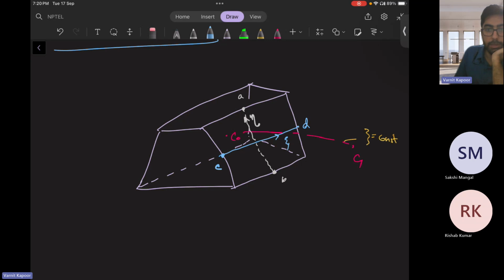So far we had only A and B coordinates. We have two more coordinates, C and D. So in total, we have four vertices, A, B, C, D, where these eta and xi need to be calculated. So if we have to write Γ grad φ dot A_f in a 3D structured mesh, the gradients will look like a three-term system. Earlier we had two terms, primary gradient and secondary gradient. But here, one more gradient will come: ∂φ/∂ζ, ∂φ/∂η, ∂φ/∂ξ.